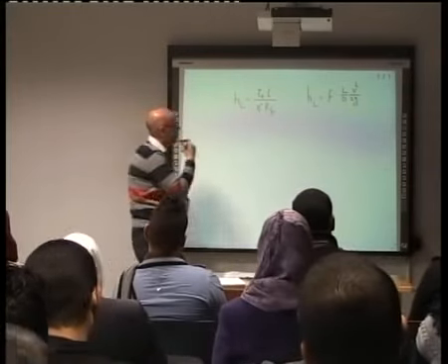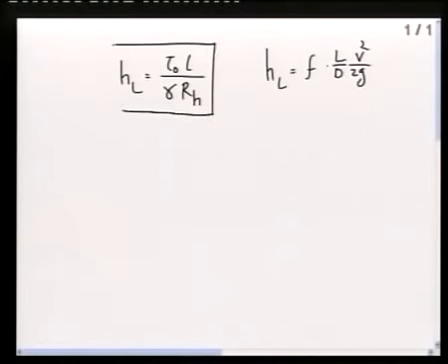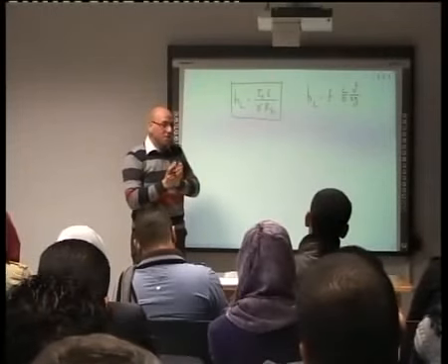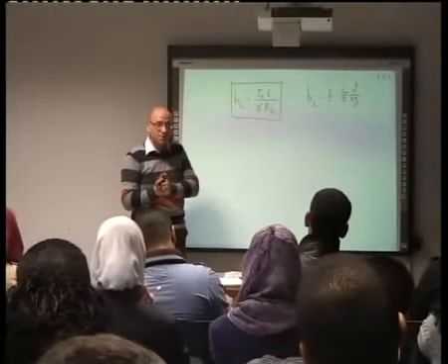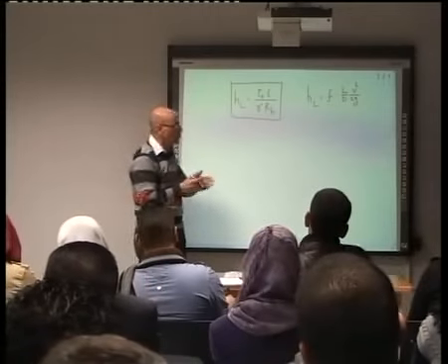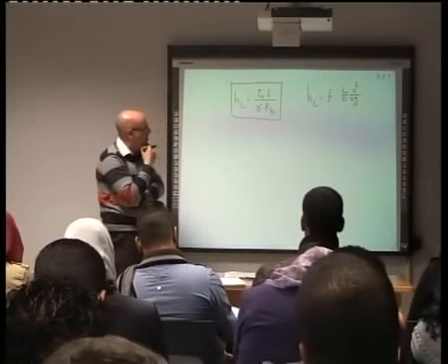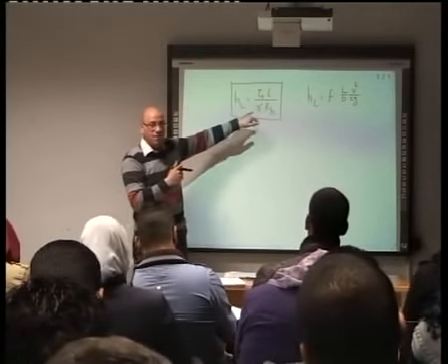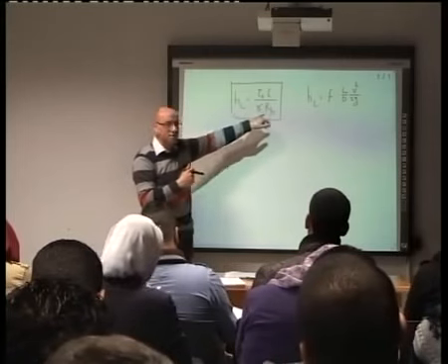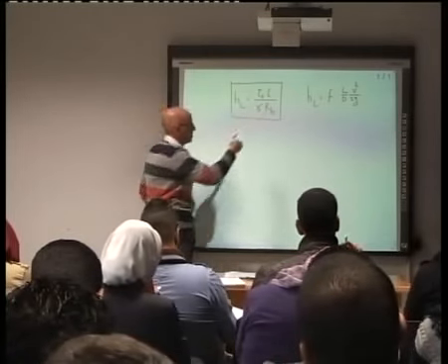If we look at this equation, what it says: the head loss in a pipe or a conduit or whatever channel is related to the shear stress at the boundary, the length of the pipe, or not necessarily the length of the pipe, it's the distance that the fluid will move, migrate, reach, whatever, over the specific weight, divided by. Now this is important to know.